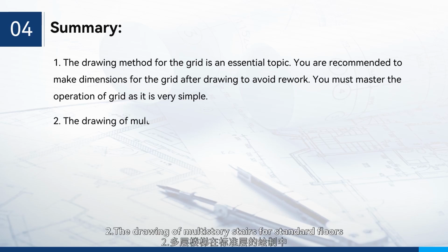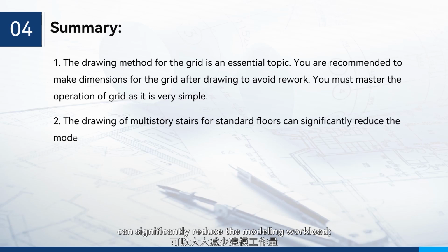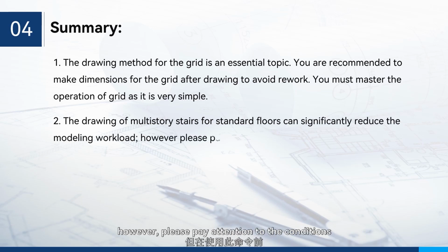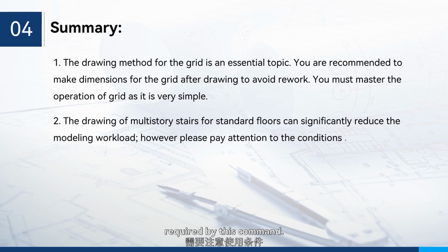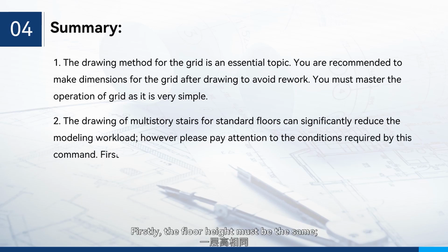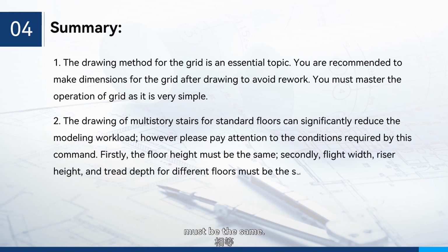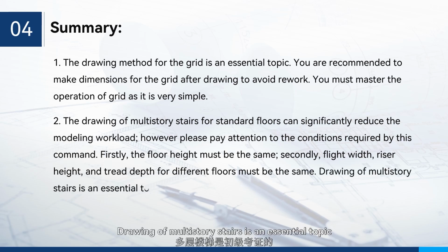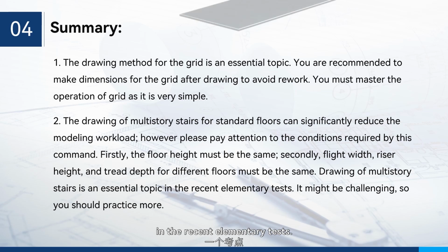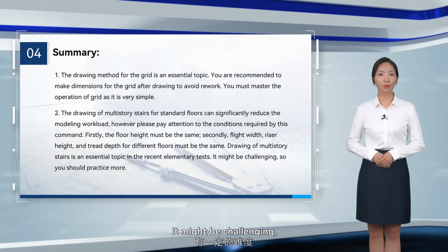2. The drawing of multi-story stairs for standard floors can significantly reduce the modeling workload. However, please pay attention to the conditions required by this command. Firstly, the floor height must be the same. Secondly, flight width, riser height, and tread depth for different floors must be the same. Drawing of multi-story stairs is an essential topic in the recent elementary tests. It might be challenging, so you should practice more.